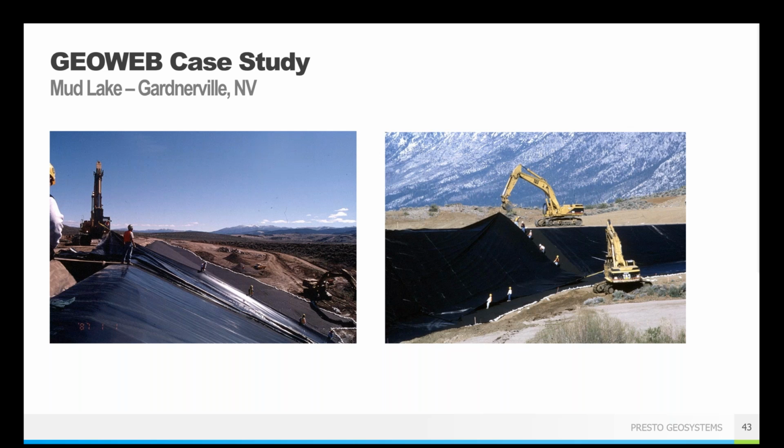In this case, the selected solution involved a 16-ounce non-woven geotextile, and then a polypropylene geomembrane, and then another non-woven geotextile, so it's sort of a sandwich. This was determined by the dam owner. This was something that they needed to meet their hydraulic requirements, and so it was something that we had to work with that was already going to be on site. This is not a typical thing to see, these sort of sandwiches like that. That is a pretty heavily reinforced geomembrane liner. But like I said, it is definitely something we can work with. If it's something that you need for your project, then we're going to work with you. We're not going to dictate that sort of thing saying yes or no.